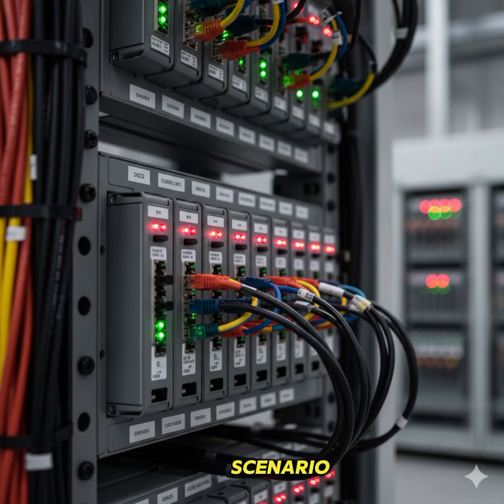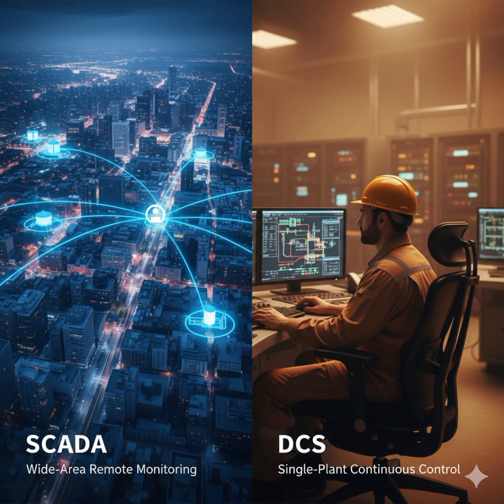Scenario 1, Water Distribution Network, SCADA. Imagine you're managing a water supply system for an entire city. You have tanks, pumps, and valves scattered across dozens of locations. Instead of sending operators everywhere, you install sensors and RTUs at each site. These devices send real-time data, tank levels, pump status, pressure, to your central SCADA software.